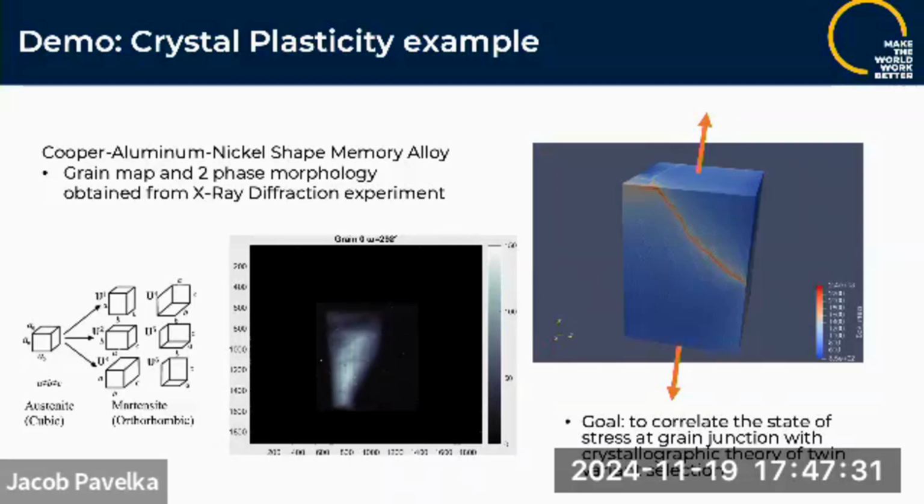So what is different about the crystal plasticity module compared to the continuum plasticity module? Well, I can define different regions in the mesh associated with different grains, and I give those regions a certain orientation. So now we are modeling the anisotropy of the material at the grain scale. And that is why we are able to reproduce what we think is happening in the mechanics of this material.